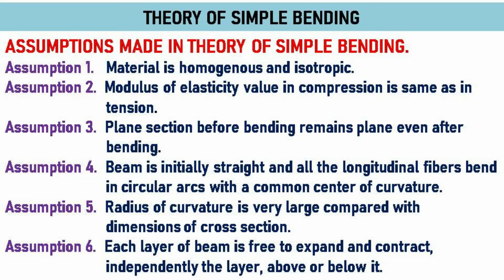Assumption 2. Modulus of elasticity value in compression is same as in tension. Assumption 3. Plane section before bending remains plane even after bending. Assumption 4. Beam is initially straight and all the longitudinal fibers bend in circular arcs, with a common center of curvature. Assumption 5. Radius of curvature is very large compared with dimensions of cross-section. Assumption 6. Each layer of beam is free to expand and contract independently of the layer above or below it. These are the assumptions made in theory of simple bending for further analysis.